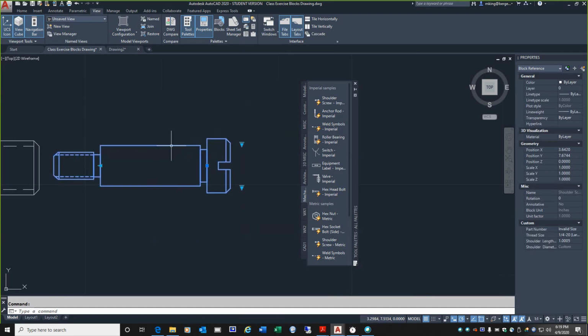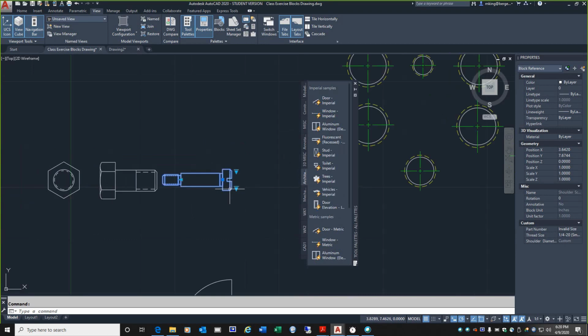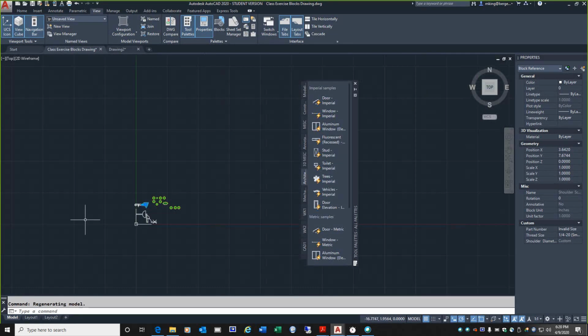and the shoulder is a large. If I go small, I believe this diameter is smaller. And let's click back on here and say small. Yeah. Okay. So these are what's called dynamic blocks. If we had an AutoCAD level 2, we would be learning that. But there's just not enough time in the course. But you basically create a block with other options in that block. Okay. And the ones with the lightning bolts are called dynamic blocks. Okay, if we go back to the architecture, and you need to zoom out because these things are big, they're gigantic, and we're in these little tiny things.